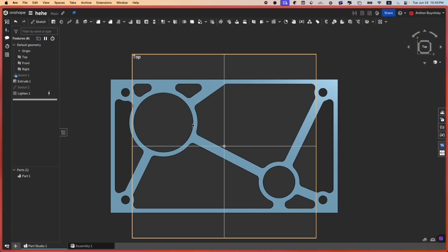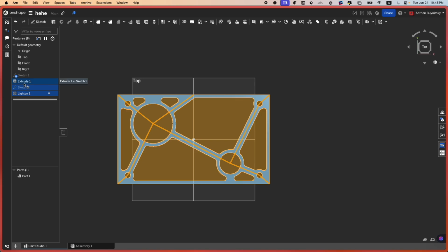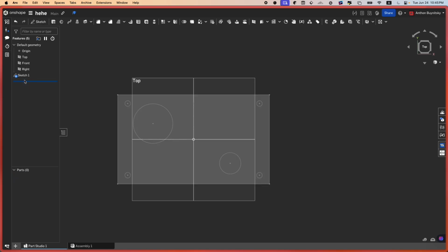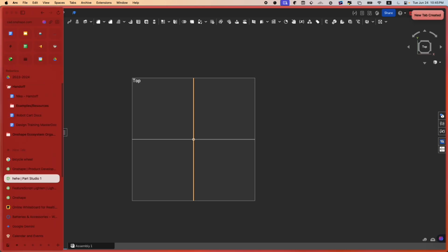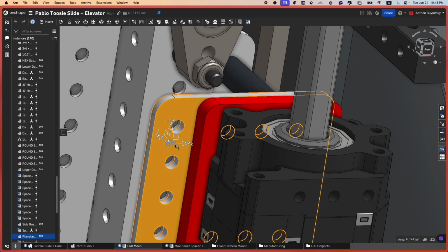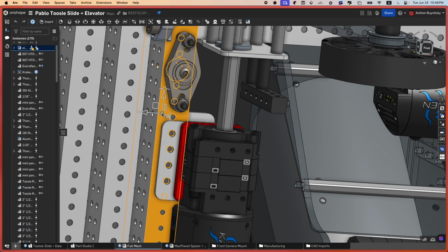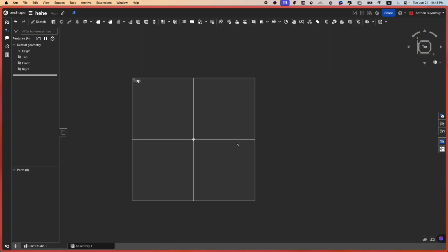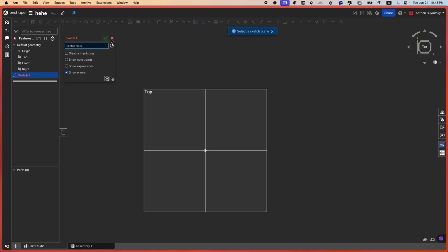Moving on to the gusset feature scripts. So a gusset is essentially a plate that connects two things together. I'll go into actually our FRC robot doc and I'll show you some examples of them. These two plates over here definitely are gussets, right? They're quite literally just plates with holes that connect one thing to another thing, right? And creating those plates by yourself can be pretty tedious, especially with all the sketch thing and the extruding thing.